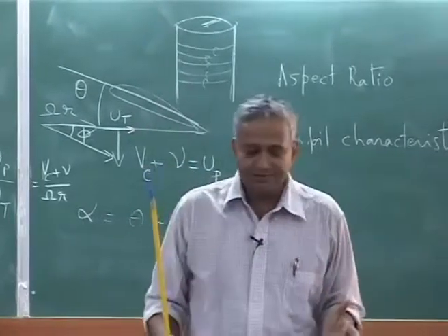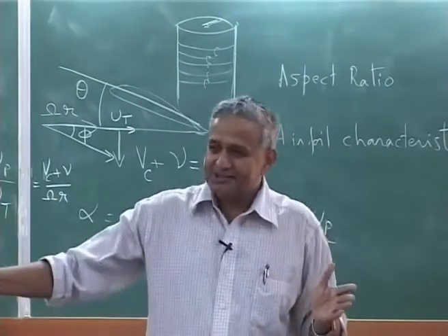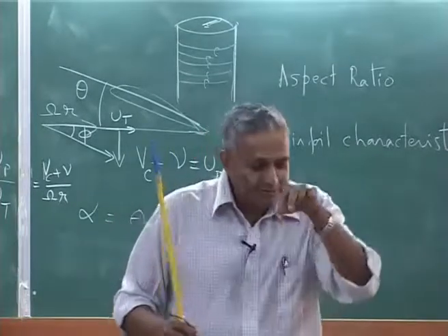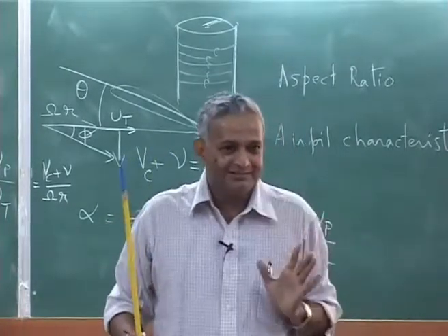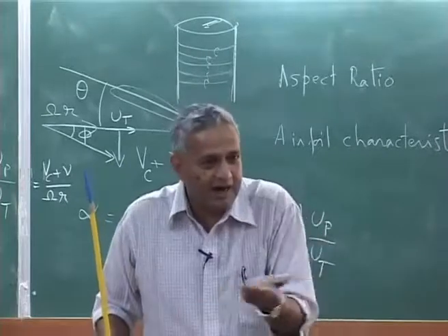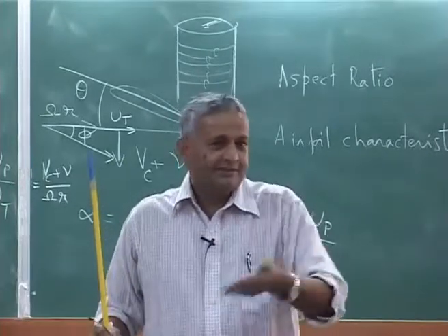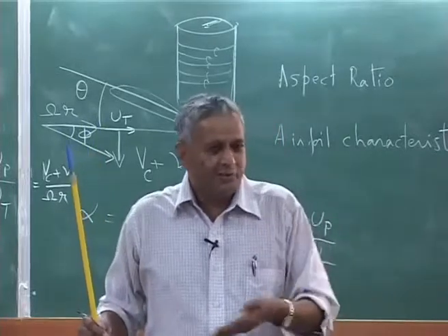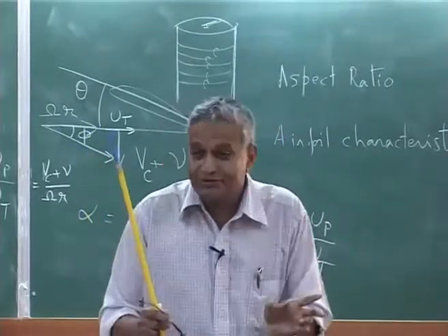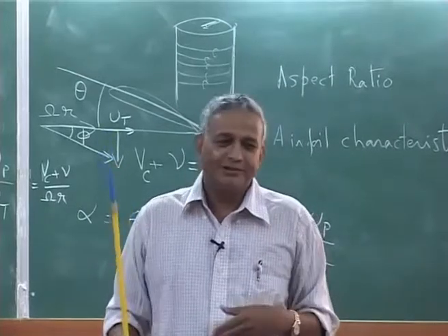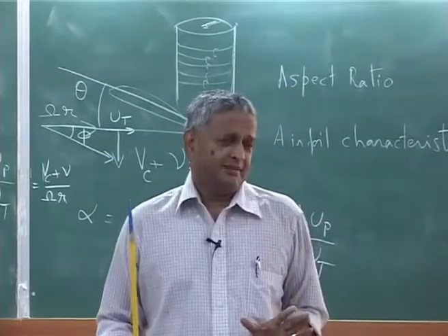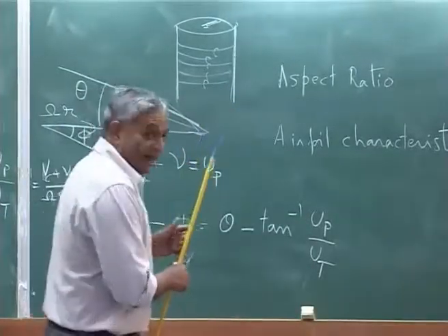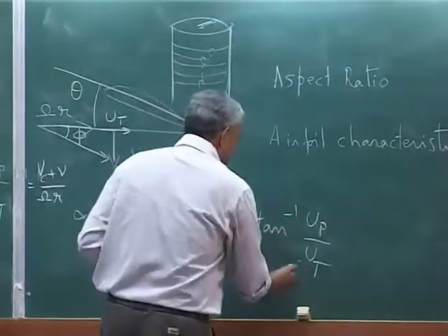But usually what happens is your aerodynamic section starts not from the center of the hub. And another thing is the omega r, the dynamic pressure due to velocity, omega r is very small near the root. Therefore, you make an error, but you say it's all right, I accept that error. So, I represent this